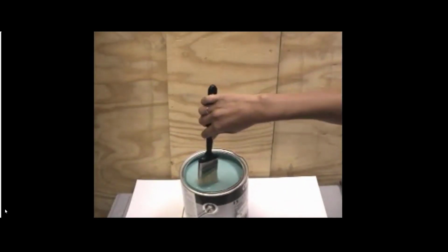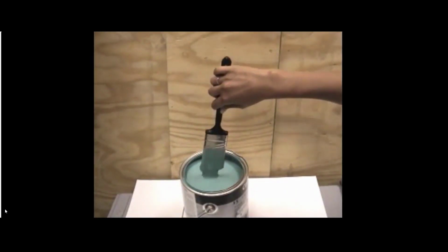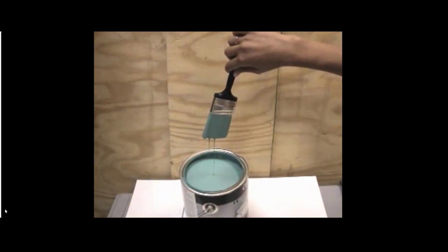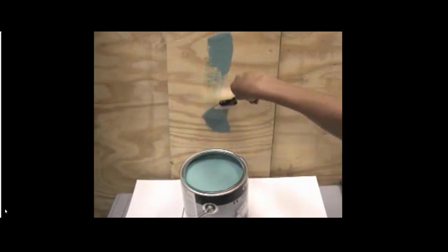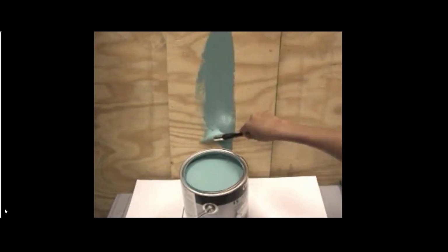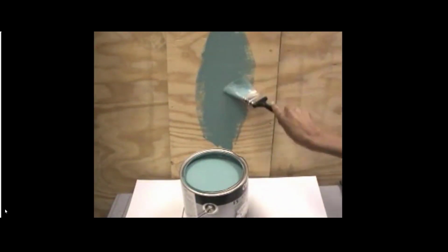You have to hit the bottle hard enough to exceed the ketchup's shear threshold, whereupon its viscosity falls and it begins to pour. Paint is another example of a shear thinning fluid. It's viscous enough to stick to the brush because the applied shear stress is small. But its viscosity drops dramatically as it's sheared, so we can apply it to a wall in a thin coating.